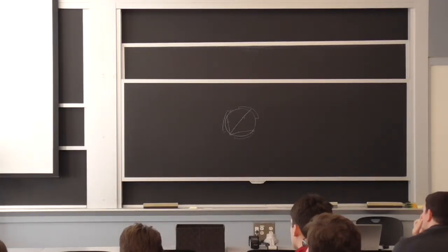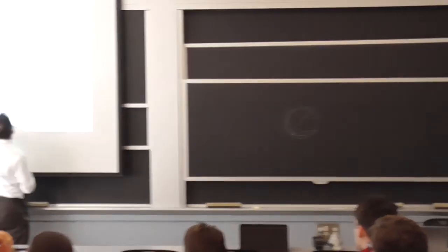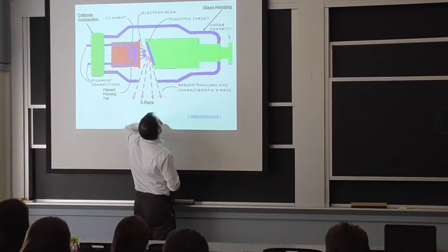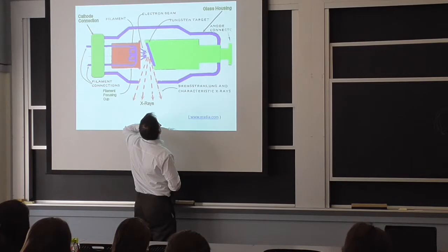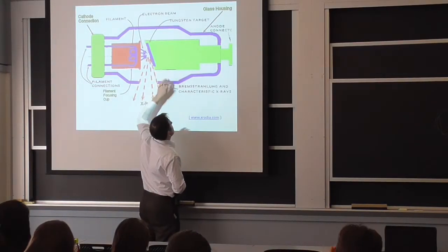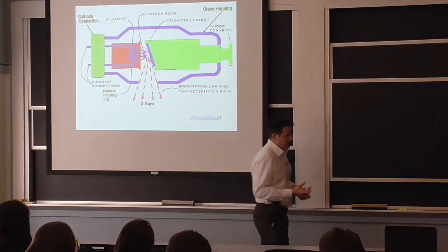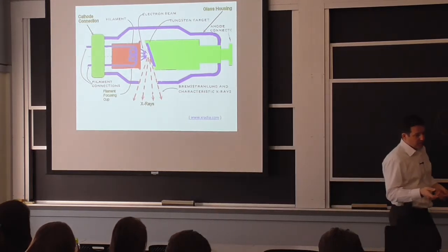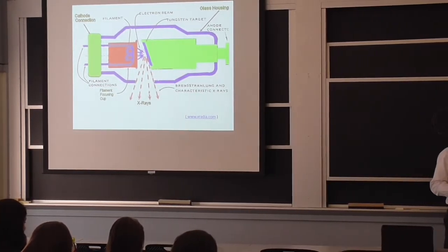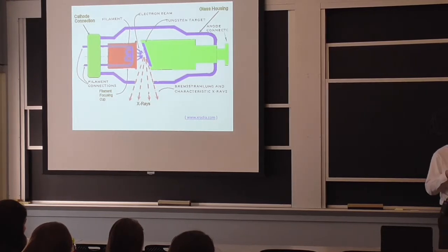You have a target material here that is very highly resistant to the heat. It's a tungsten alloy, and then what's in green is essentially a cooling system that picks up as much heat as possible. There's a fluid, and there's a number of channels circulating in there to try to maintain the surface temperature below a certain value.